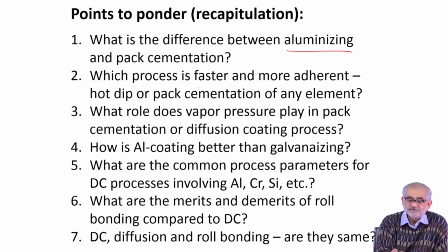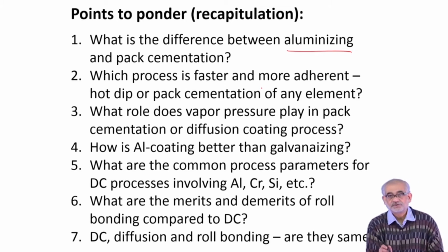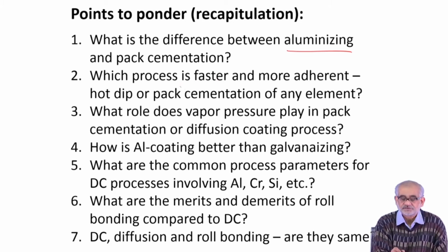Obviously in the hot dip process, you are exposing to not only high temperature, but you are guaranteeing very wide, very good coverage of the entire surface area. The process can also be faster because it can be a continuous process. So you can pull from one end to the other and make kilometer-long strips coated with aluminum and coil them into large coils at a faster rate.